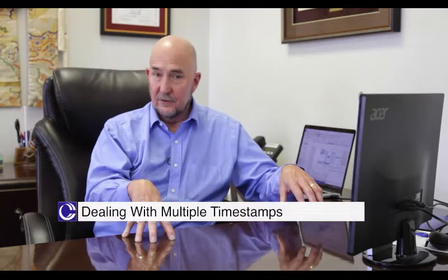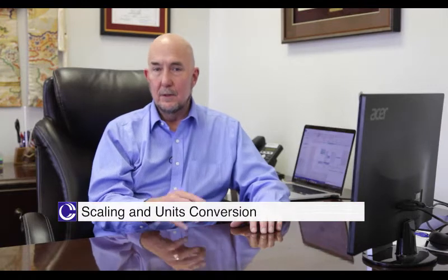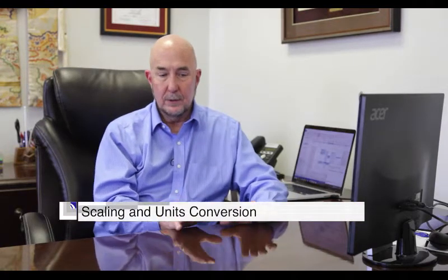Once you've done that, of course, you have to make sure that the timestamp of the data that you're sensing is aligned and consistent with the data from the process tool, because if you have a shift in that data, then you will end up with invalid or erroneous results. Of course, the other issue is that the binary representation of the data that you've sampled may be different than that which comes from the equipment or other sources, so you may need to do units conversion and scaling to put those in the same engineering units.